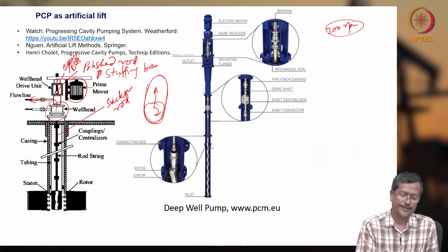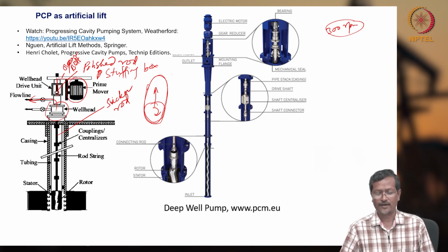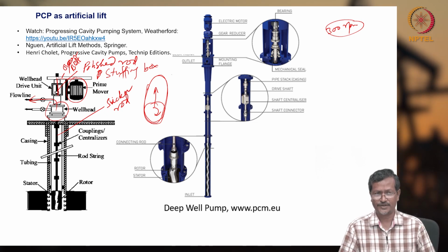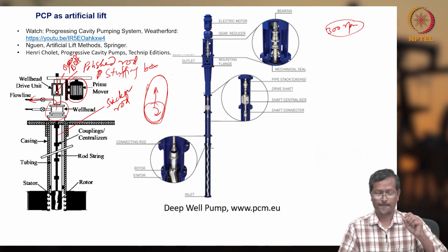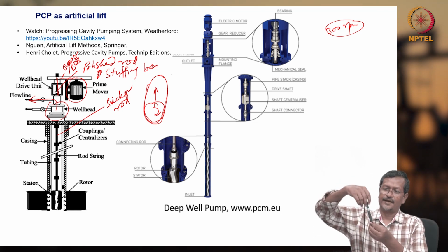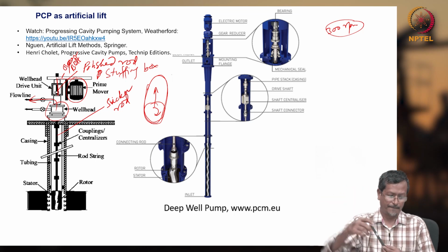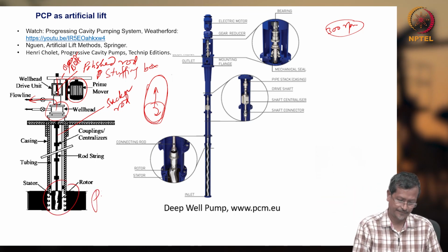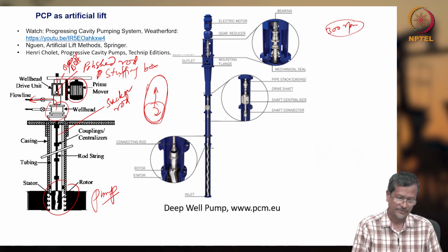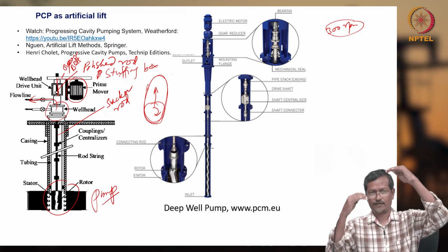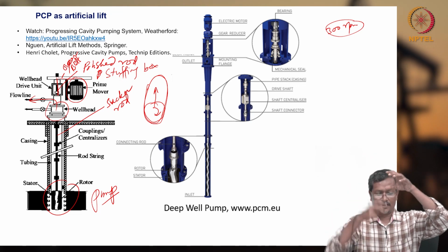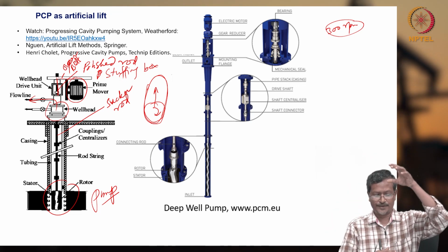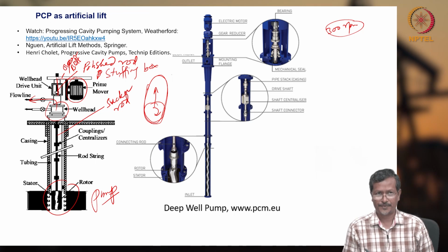Okay. Sucker rod, normally it will not have tension force, it will be transferring torque. So, from here you are rotating and it will be transferring torque to your pump, which is here at the bottom. So, on the surface you have all the drive mechanism, stuffing box, polish rod, and at the bottom nearby the perforation area you have the pump.